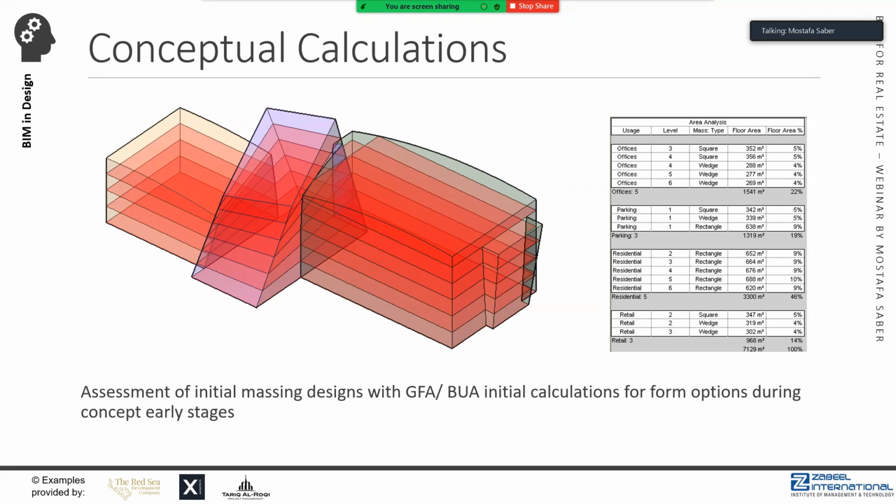You can imagine that creating options like these and figuring out the impact on feasibility, the impact on the project cost for such a type of building is possible within a few days, or let's say a few hours. You can simply start creating simple masses inside programs like Revit, and then using this information, you can extract schedules like the one you see on the right side. It has area analysis, and you can also relate it to cost.